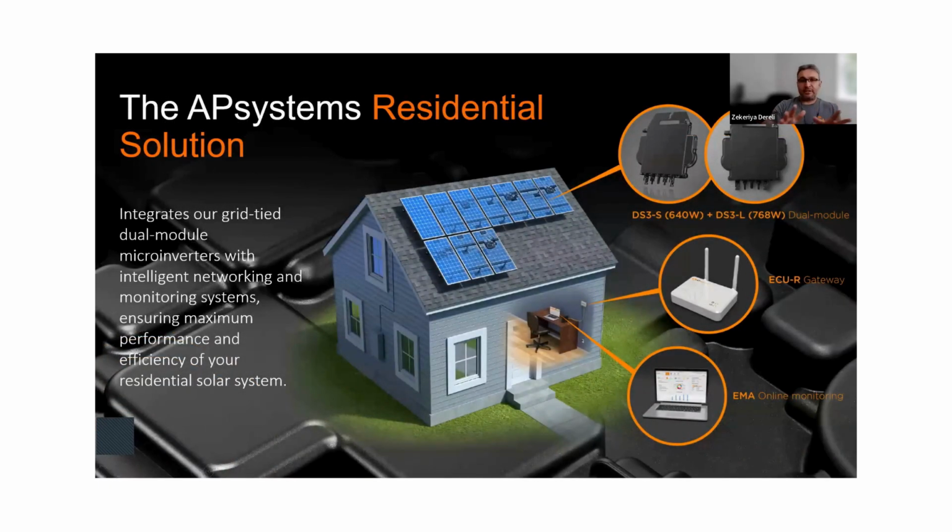Okay, the typical residential application. Microinverters are very suitable devices for residentials, almost a no-brainer. You get a microinverter that connects to two modules. In the past it was single module, but two modules is easy enough per microinverter in terms of installation. That also reduces your BOM and the number of micros you will need. So two seems to be a good fit. But today we will also introduce quad microinverters. Hopefully that will be exciting for you guys. But so yeah, two or four for residential.